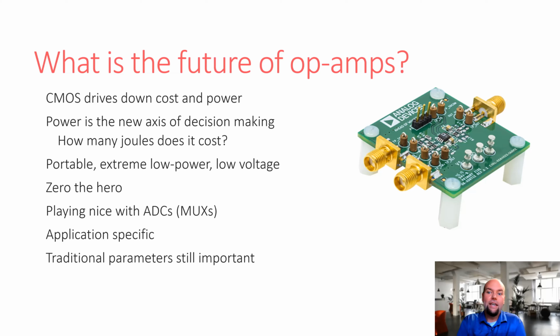Well, how does it do that? It does have to be measuring. It has to be constantly measuring that load cell to detect when you're pushing your foot on it. What's happening typically in a lot of these designs now is they have a special op-amp circuit that uses almost no power. It does amplify the signal, and it's typically doing a differential measurement. So it's looking for that change, that slope of strain, as your foot pushes or releases off the scale. It's really just a very low power circuit that measures this differential change in resistance.